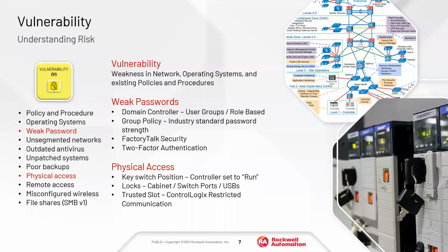Also, the use of a dedicated domain controller, something that's part of the control system environment that provides you the ability to manage group access, what we would consider a security authority, something that's providing access that we can leverage. Those policies would be set on the roles like operator, maintenance, admin, and you can have those roles be part of the domain controller and then use FactoryTalk Security or another mechanism to pass that along to the HMI.